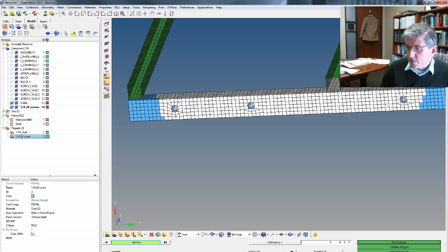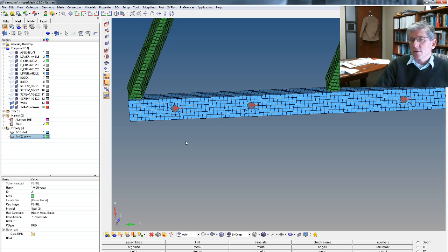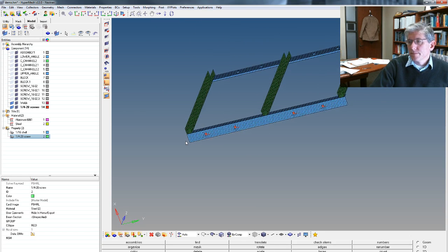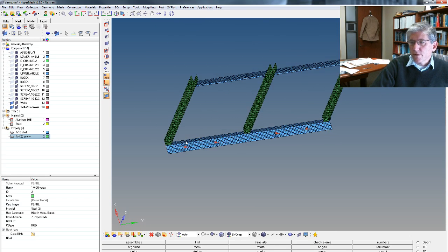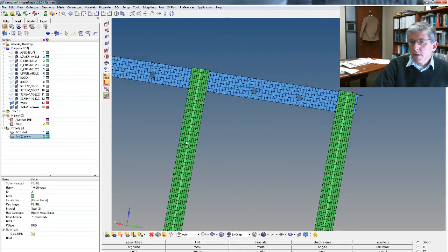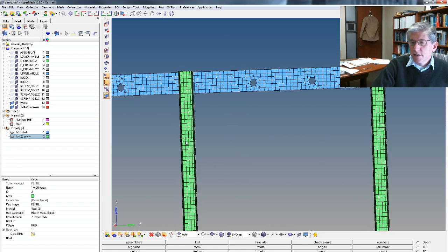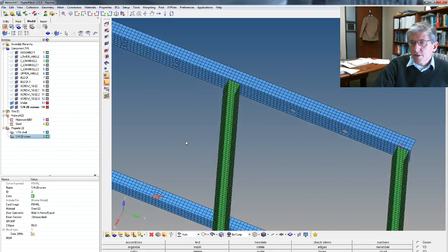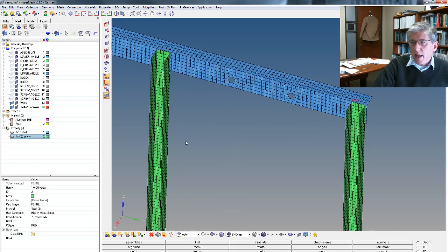So this preview is good. And that looks good. And see, it's just doing the ones that I think it should. So we'll equivalence and that's fine, and now they're actually connected, okay? All right, so we've put the fasteners in, and we've done a weld, and actually, I guess the one other weird thing we could do is we could add a concentrated mass.